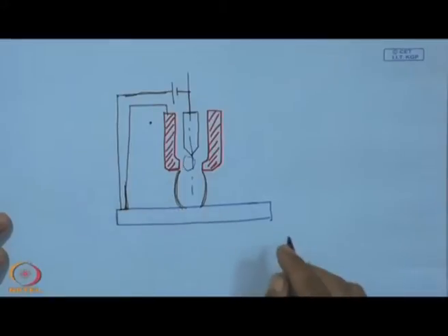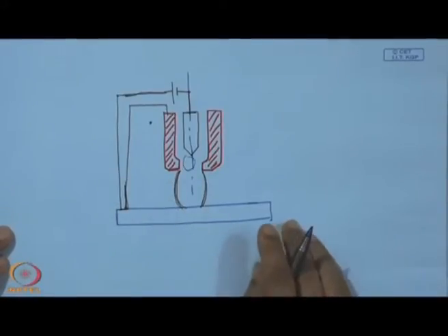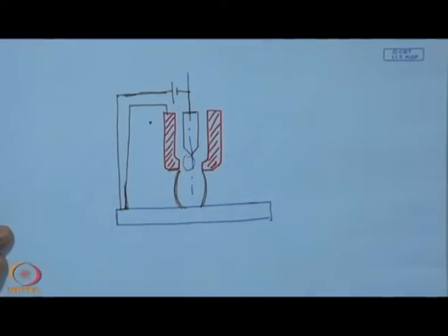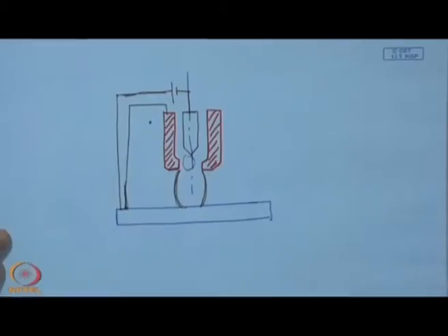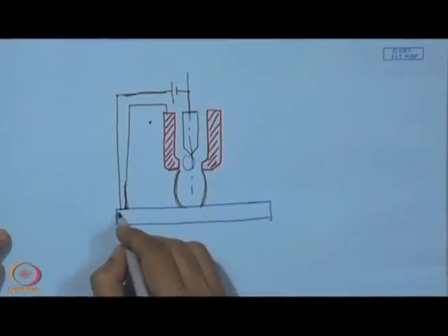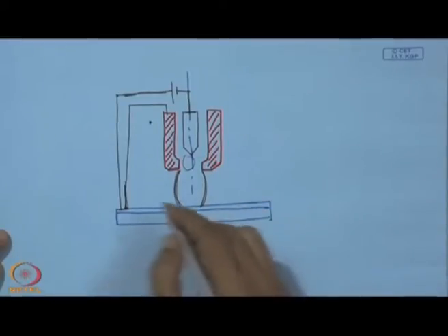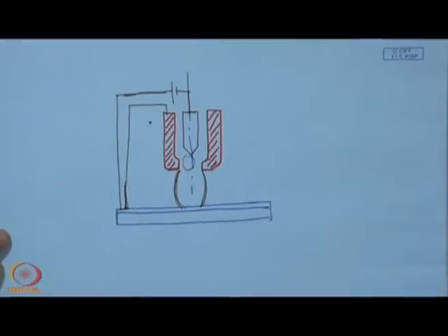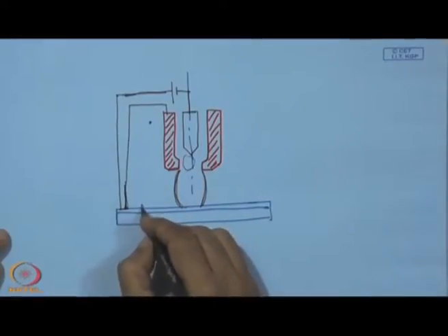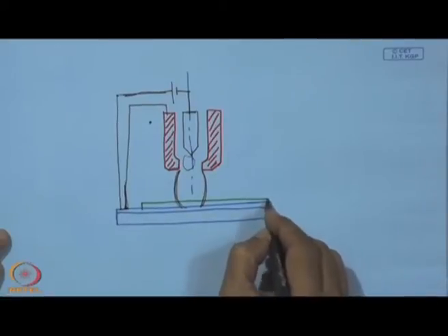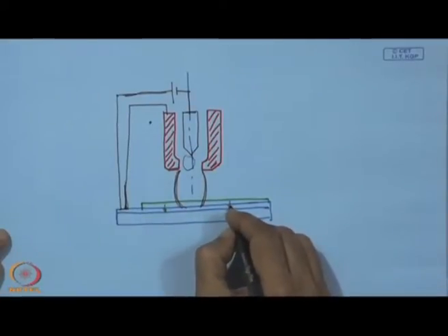The whole idea here is to have some kind of metallurgical bonding, that means allowing this coated material to have some sort of diffusion within the substrate. By that process the top surface of the substrate may be diluted by this coating material. So, if we have a coating material over this, it may get diffused into this by this melting.